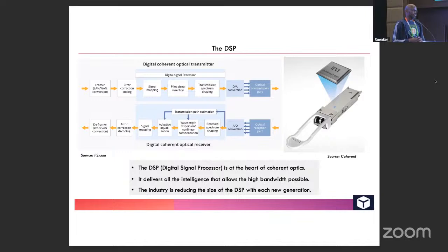dispersion compensation anymore in the fiber itself, which is how subsea systems used to get built, which is how fibers used to get built. If you look at Japan, for example, Japan is pretty much the only country that built dispersion shifted fiber, which was great back then, but you don't need that anymore. That means that you can run uncompensated fiber, which is much cheaper. In fact, with coherent, the more positively dispersed the cable is, the better the performance of coherent infrastructure.